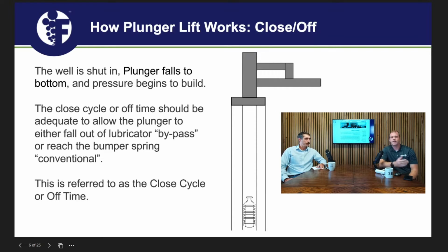Good point on that. Because since this plunger is essentially free traveling, you're saying that sometimes it may travel too fast up to surface at too high of a velocity, and that could damage the lubricator itself, which is not good, right? Or it could damage the plunger. Typically just breaking it? Is that what you see? Right. Yeah. Okay. Just material fatigue from those impacts.